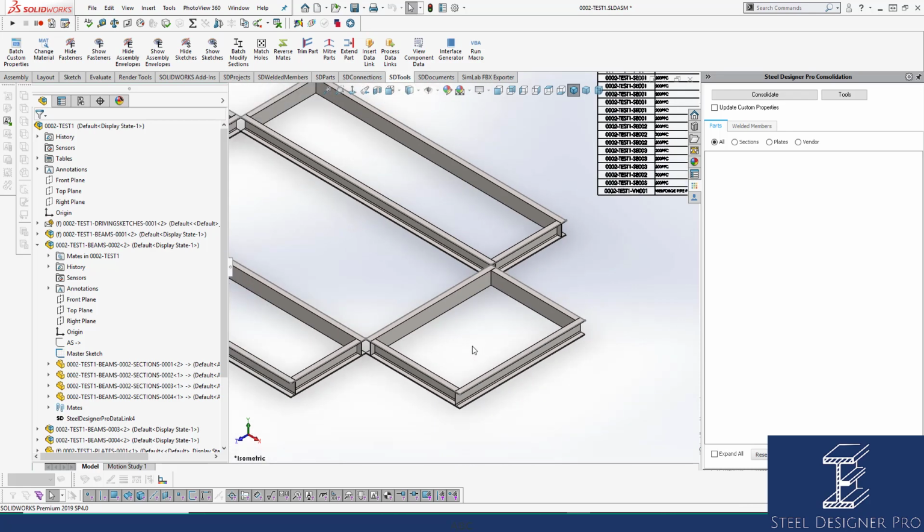Now that I've changed it, it means that the marks are going to change, because when I run consolidation, I've just done a Control Q and a Control S, but when I run consolidation, you will see that the 8 will drop to 6 and there will be 2 more new section marks in play. So when I consolidate, you can see now that the 6 has dropped off, but we've now got 2 more items that have occurred. This potentially can happen, so just be wary of that.